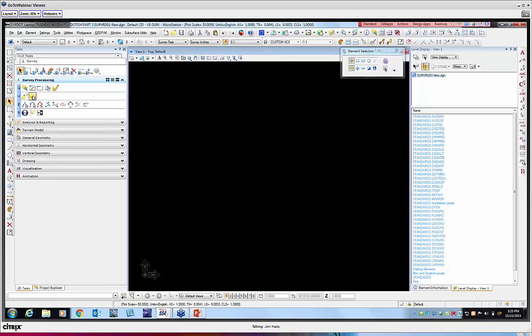Okay. You can load data directly from here. You can also edit. These are chain editing of linear features. And then you have your reports, and then finally there's a way to turn on and off annotations, specifically point annotations, point names, elevations, descriptions, using this tool right here. So this is your civil task menu, and it is very important to the overall workflow.